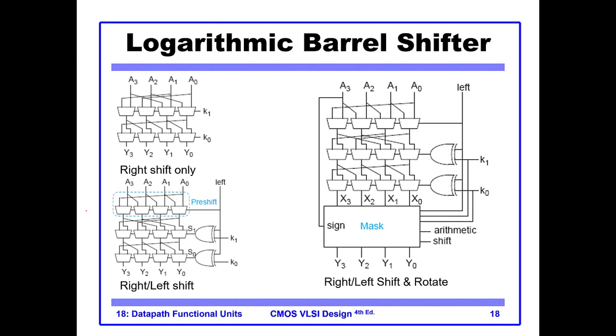Then there is this barrel shifter, which is sort of a universal shifter. It can shift right, it can shift left, or it can rotate. Rotate is basically, this is called shift right and rotate, where you take the final thrown out bit and feed it back. So that is rotation. So go through these circuits. They are just multiplexers, and check how they are implementing the right shift and left shift operation.